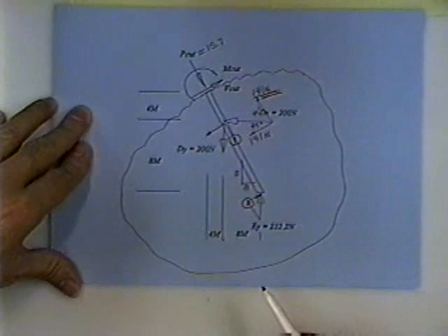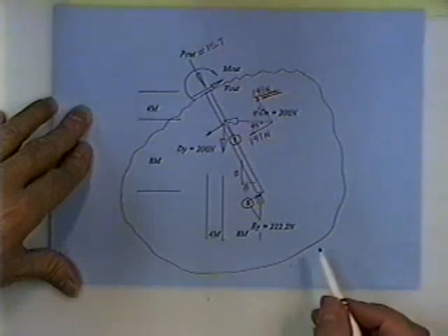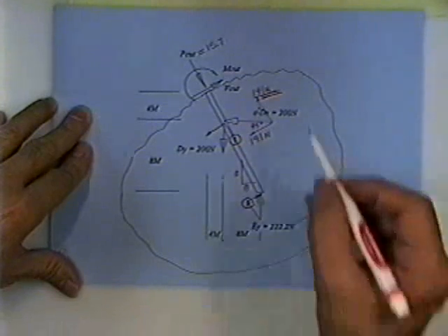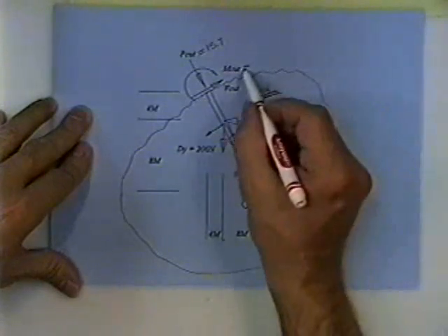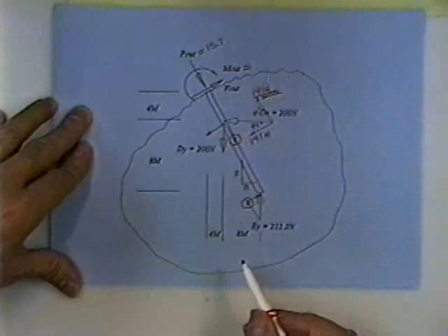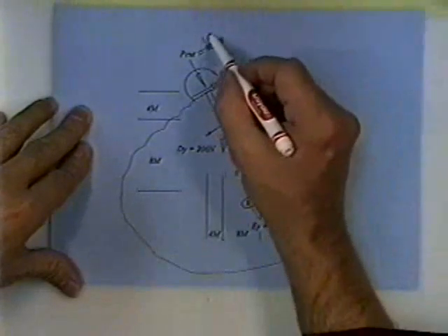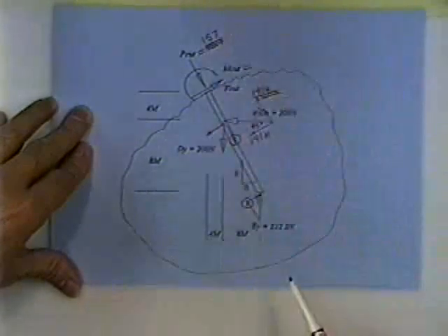You do the same thing for V, the shear across the axis of the member. You simply sum forces in the transverse direction. And then to get M cut, you simply multiply each of the forces times their moment arms. I don't care about V cut. Let me get M cut. Well, this one right here is 157. Yeah. Sorry about that.